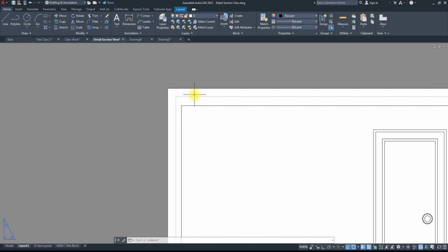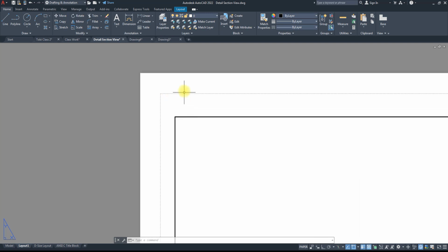But if you look at it, there is this dotted line, this dash line, and there is this continuous line. So this dash line is the printable margin, meaning anything that is within this dash line is what will be printed. So if you have any object outside this dash line, it will not be printed. So it's more like the margin that will be printed. So your printable margin. So that means if I have something like this now, and I want to print, only this place will be printed. The top parts will not be printed because it is past the printable margin. All right. Am I making any sense? All right. So that's what the dash line is.